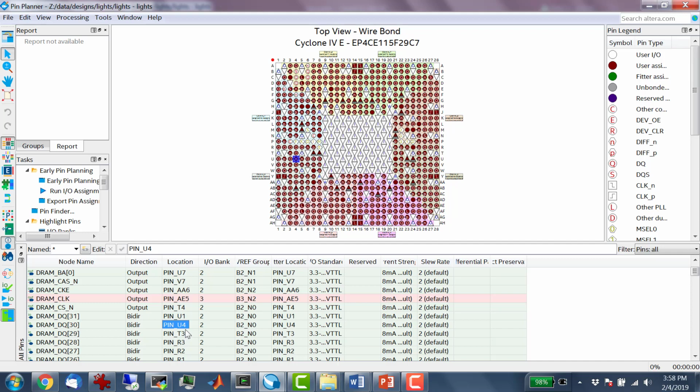But on a complex chip like an FPGA, you want more pins than are available just on the periphery of the chip. So you go underneath the chip and take advantage of that whole area to get as many pins as you can. There are 800 pins on this thing. Why so many? Because the FPGA vendors want to provide as many pins as they can so you can use them for whatever you want to.